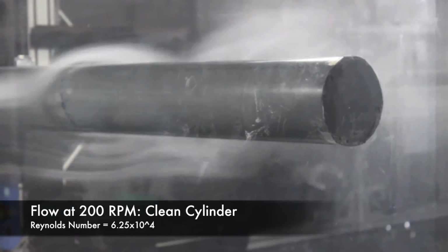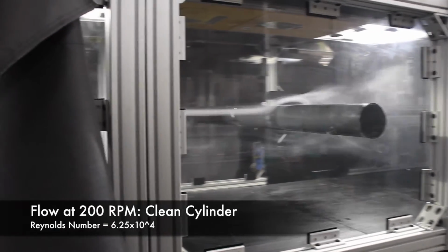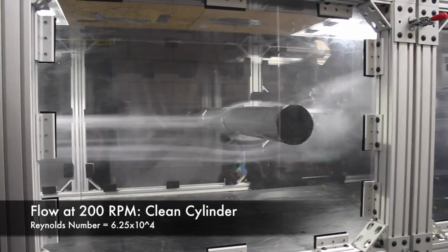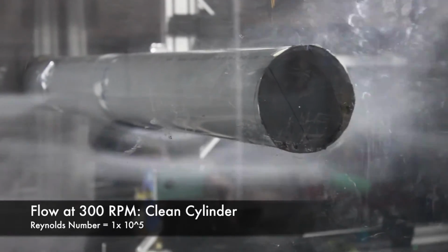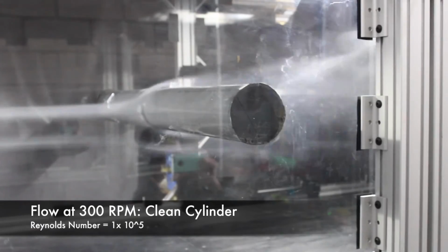Then the wind tunnel was turned on to an RPM of 100 and a settling time of 30 to 45 seconds was allowed before collecting data. While data was collected, video and photos of the flow around the cylinder were taken using a Canon DSLR camera and slow motion video was taken using an iPhone camera. This was then repeated at RPMs of 200 and 300.